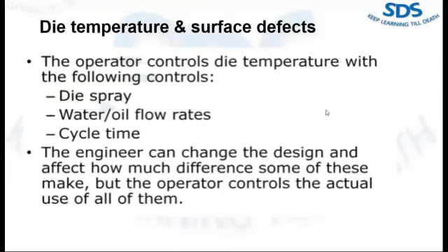Some people use water to cool down the die, and some people use oil, which is called a mold temperature control unit, in which we use hot oil to control or maintain the die temperature.